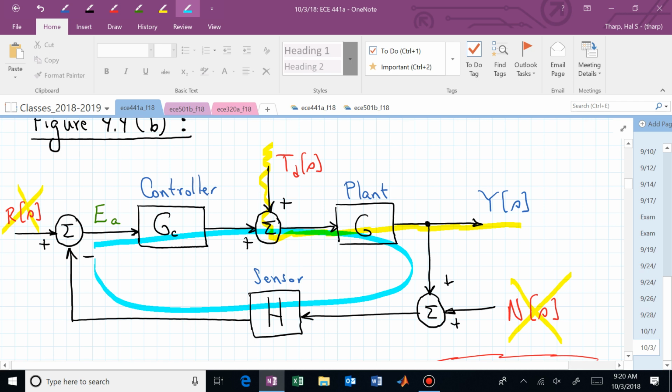And what happens now if I want to find the cofactor for that path? What's the process involved in finding the cofactor for a path? You virtually erase that path and see what loops were disconnected and remove those disconnected loops from your determinant expression. And boom, we have the cofactor. We only have one loop, we only have one path, we have one cofactor to play with.